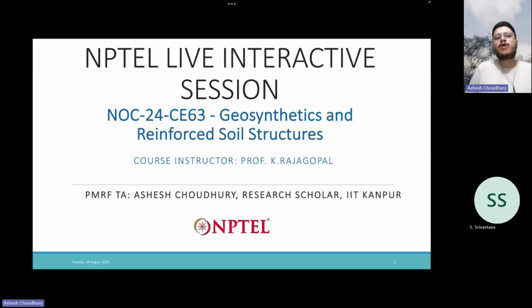Second is the internal. Now how are you going to satisfy the internal stability criteria? The answer to that is the spacing. The first is internal stability, rupture stability. The reinforcement should not rupture.